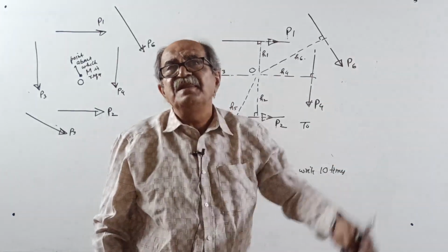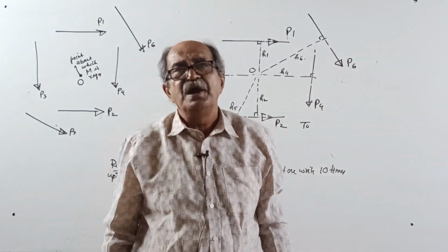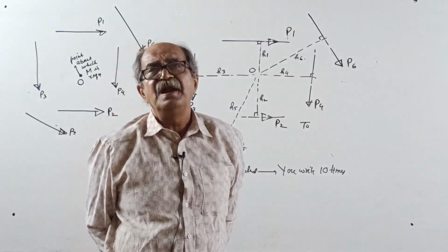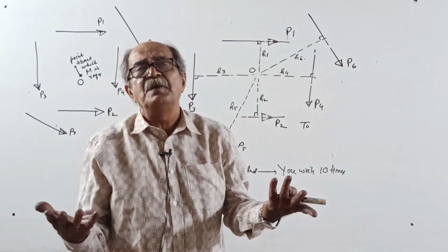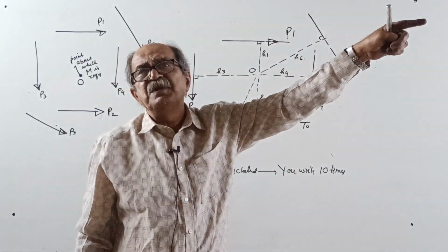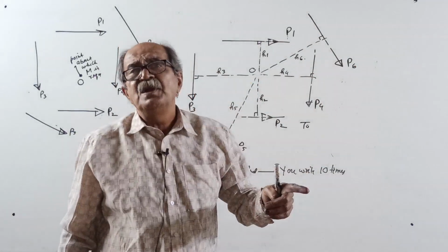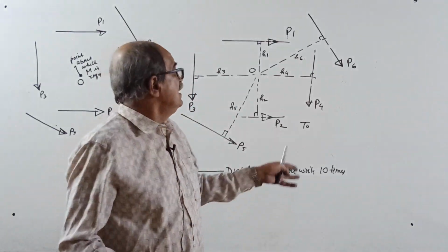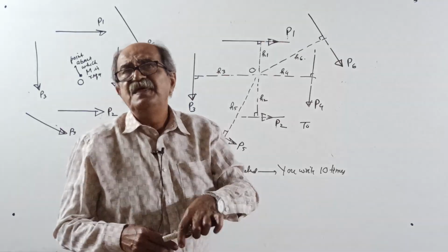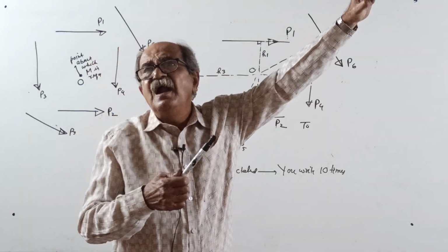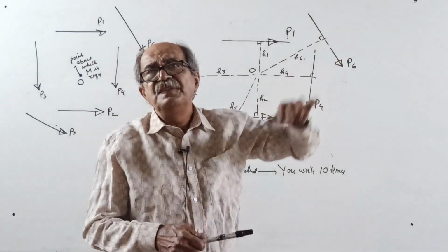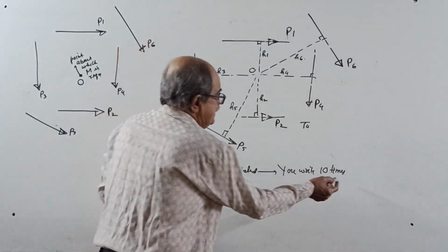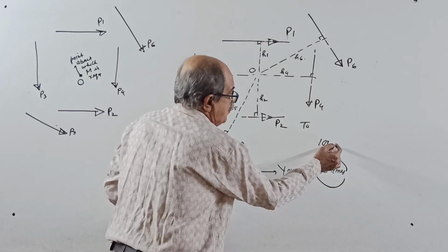But if the force is inclined, what you can do is resolve the force into horizontal and vertical components. Then there is no problem. Horizontal component multiplies with the vertical distance, vertical component multiplies by the horizontal distance. Or you can keep the inclined force inclined, then drop a perpendicular, find its value, and multiply by that perpendicular to the line of action of the force. Write it 10 times or 100 times if you want.